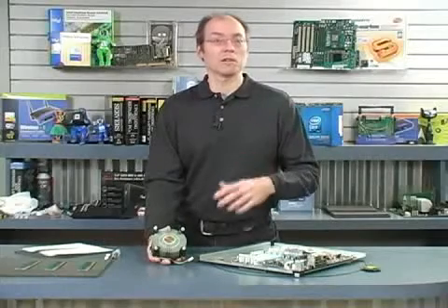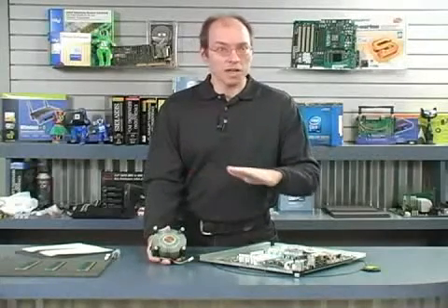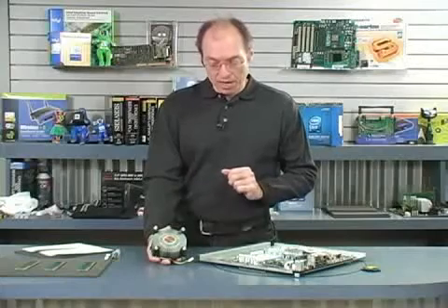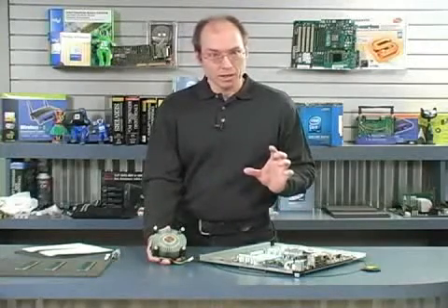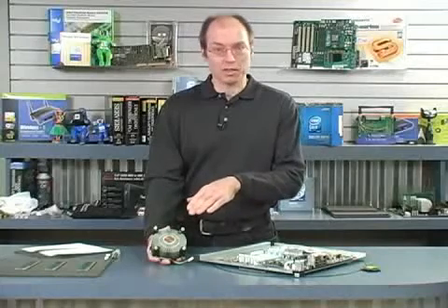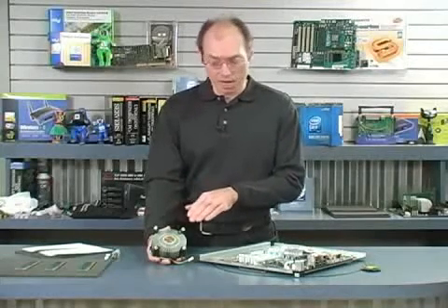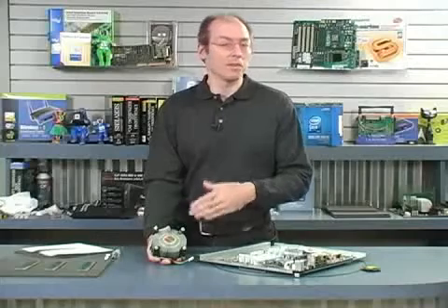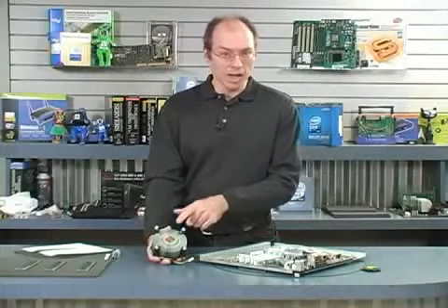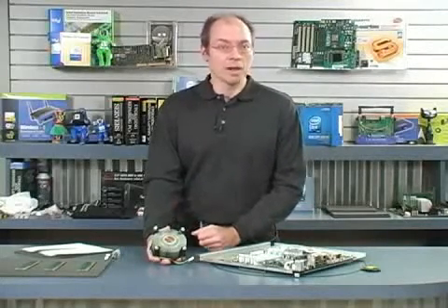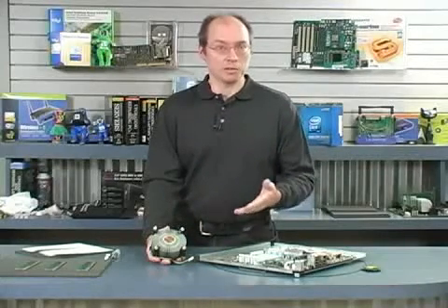Once the processor is first powered up, that stuff will melt, and then it will ooze to where it covers the entire top of the processor. Now, with any thermal interface material, once you remove the heatsink, you have to discard that thermal interface material. It has to be cleaned off. Usually you can clean it off with a paper towel. Sometimes you need alcohol to help dissolve all of it. You want to clean it off the top of the processor and the bottom of the heatsink. Every time you reinstall a heatsink, you need to use new thermal interface material.